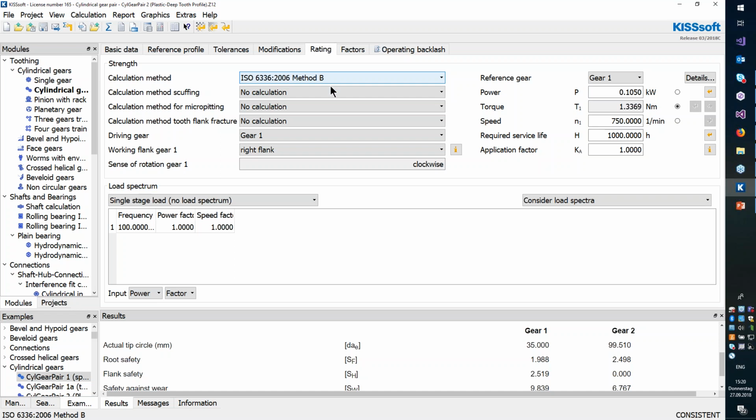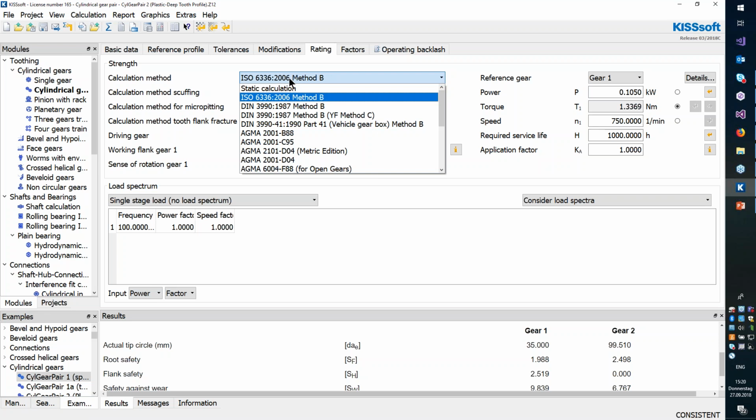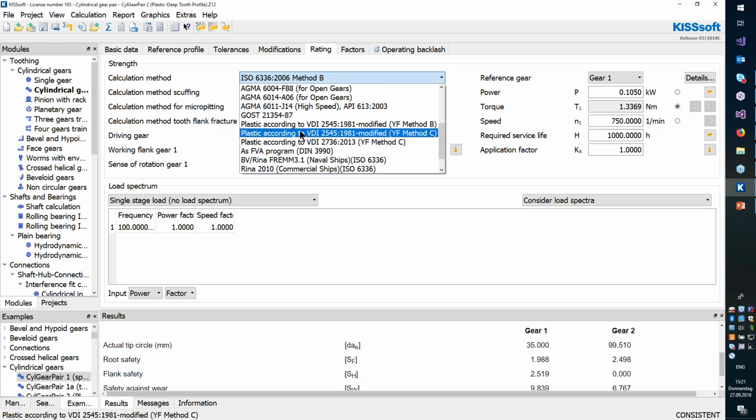One good benefit of plastic gears is that we are not limited by the traditional manufacturing processes. It means that we can change the tooth, for instance, in the root area, to increase the strength without changing the price of the part at the end, because usually we are manufacturing it with injection molding. We have some options here to improve the strength of the gears.